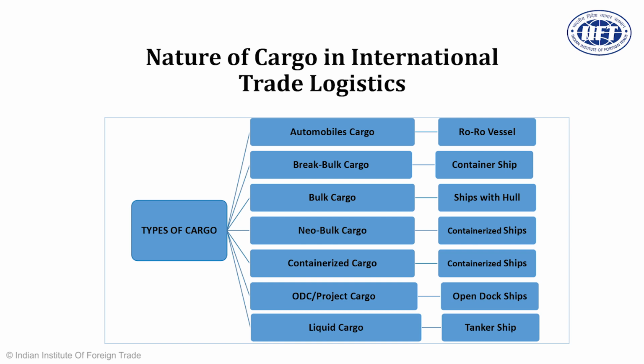And then there is liquid cargo, which usually transports gas and crude oil. They are almost around 40% of the global fleet. Tankers are of different types. For example, there are tankers known as Panamax, Suezmax, Aframax. Then we have VLCC, very large crude carrier, then the ULCC. Now the size is increasing as technological developments are taking place.